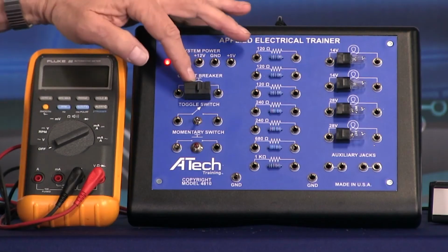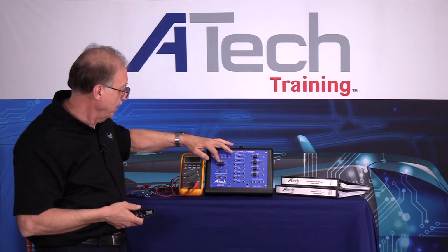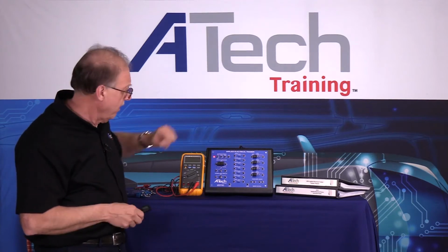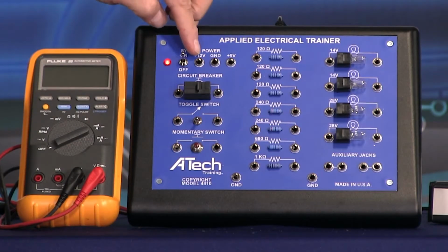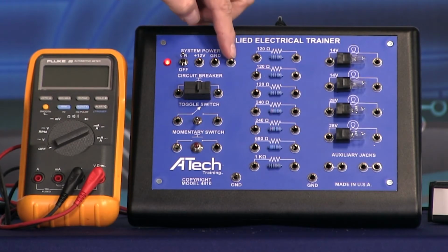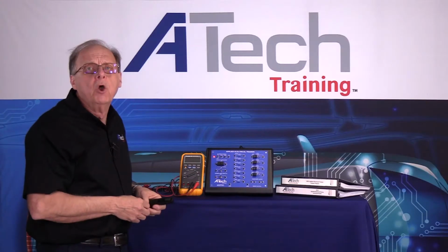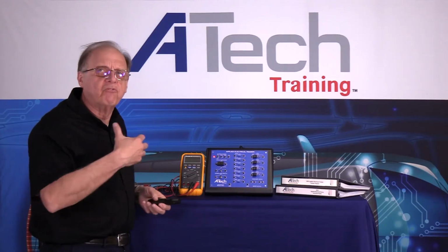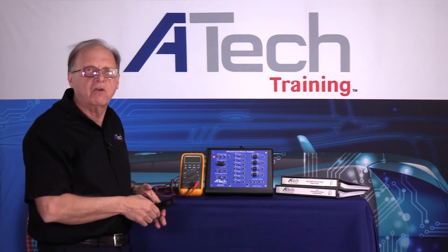We have a circuit breaker. We have to have some kind of breaker or a fuse in the circuit, so we are going to use a circuit breaker in there as our protection device. That's on this side. And if you notice, at the top we have 12 volts, we have ground, and we have a 5-volt signal, so I can put 5 volts out. If you were testing a sensor, or you just want to use a 5-volt reference to show how things change, you have the 5-volt jack there.